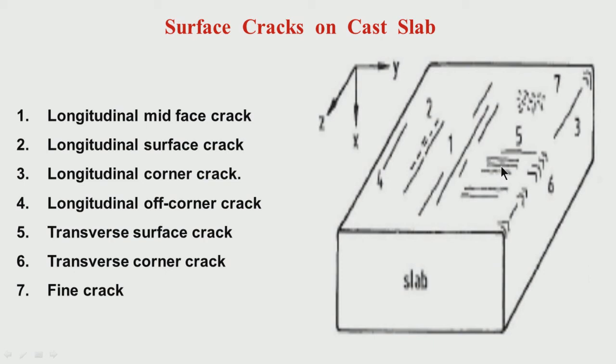You might have transverse crack at the region of deep oscillation marks. You may have transverse crack in the region of transverse depression. So, everything is depending on the direction of the strain. If the direction of the strain is transverse, it will generate longitudinal crack. If the direction of the strain is longitudinal, it will generate transverse crack.